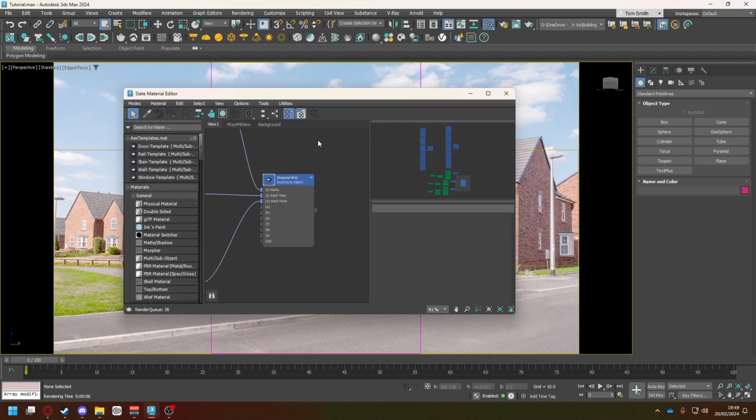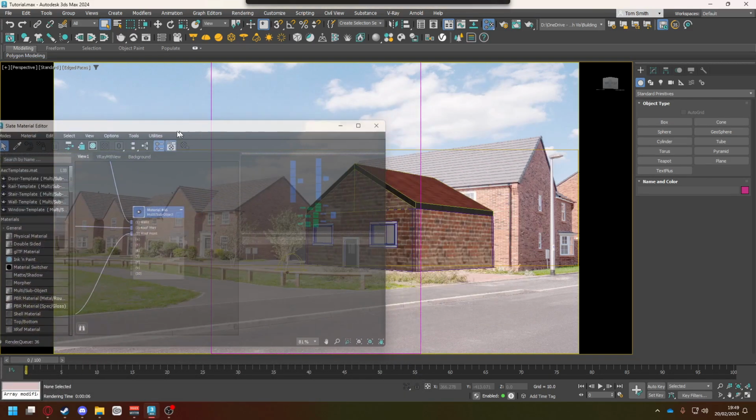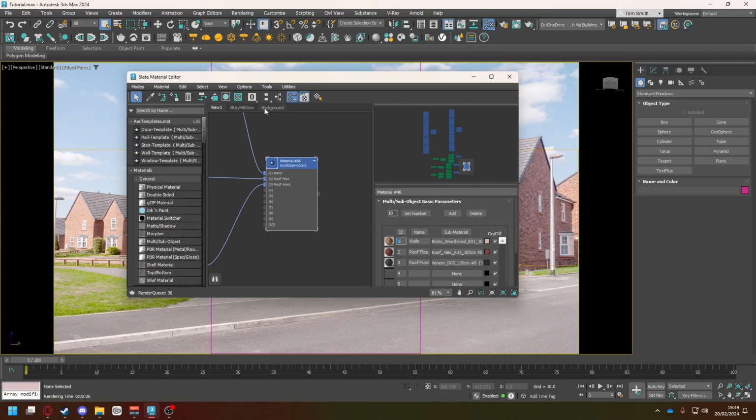So, if I wanted to select the entire building, for instance, so the walls and the roof, I'm going to select their multi-sub-object, and you see this 0 here. You click on this, you can assign it an ID channel. Now, because we're only going to use one multi-mat element, we're only going to play with channels 1, 2, and 3. So I'm going to assign this sub-object to ID channel 1.